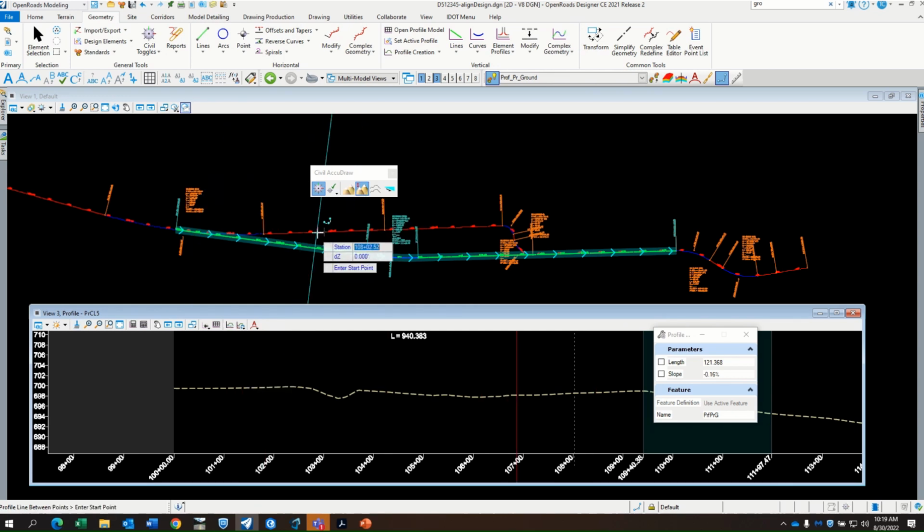It was kind of stuck in offset from when I was working horizontally. If that ever happens, just go back, select another tool, and select the one that says Z value. Now I drop down and notice that that's the choices that I'm getting, station and Z, which is what I want for a proposed profile.